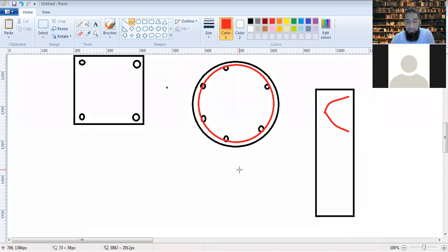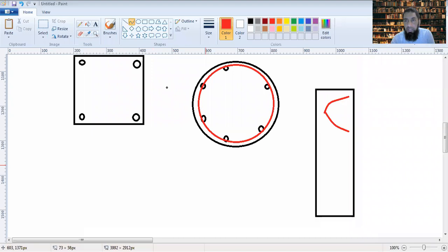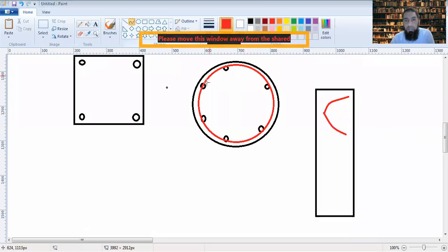So what I was discussing is the helical reinforcement, that goes like this. Now this helical reinforcement should be between bars, 6 bars minimum, wrapped around 6 bars. There will be bars like this.